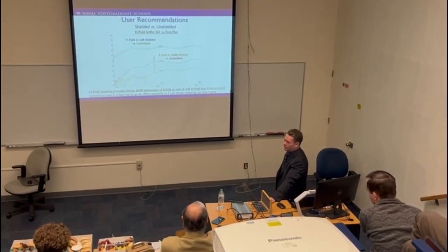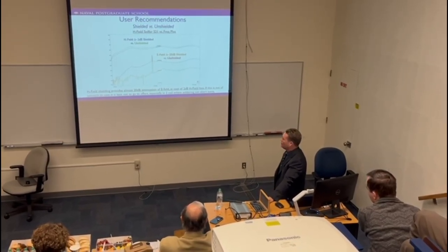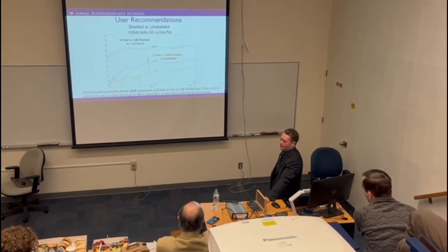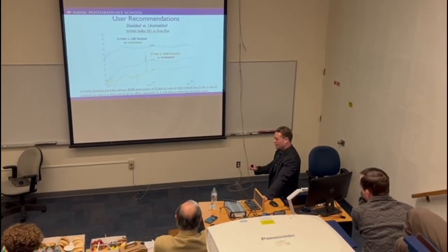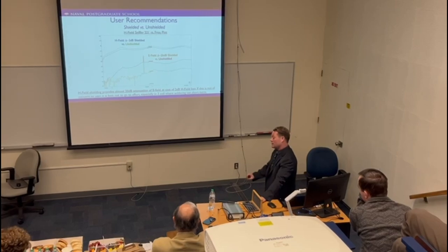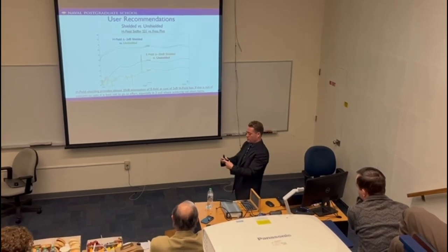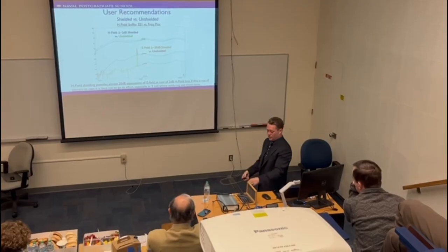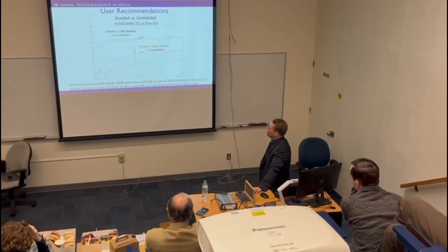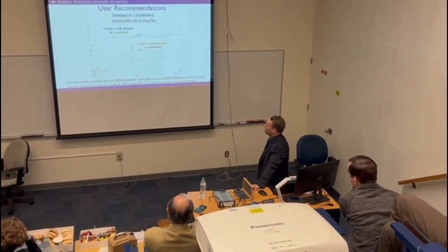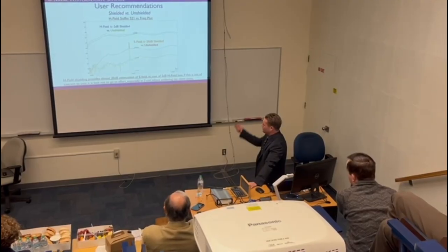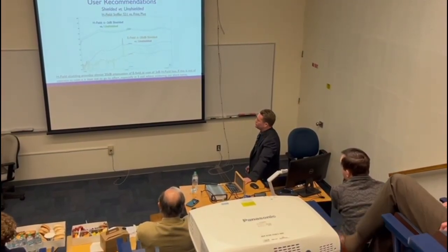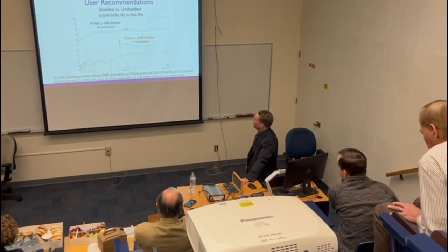The shielding is very effective. It cleans up your trace. But the manufacturing process of doing it is not easy. You need to essentially spot solder it and create a very unique little insulation section. It's not easy, but I think that it's worth doing because of the effects. I can totally decouple my E field from my H field and clean up the signal as well.